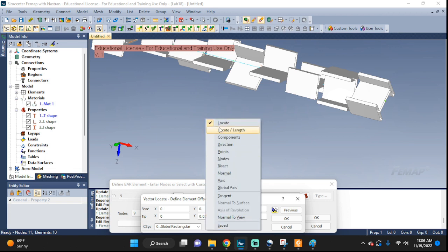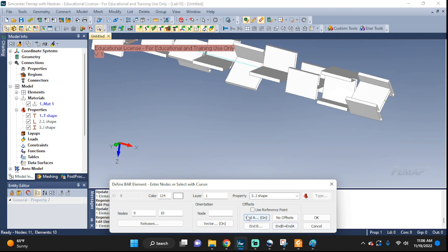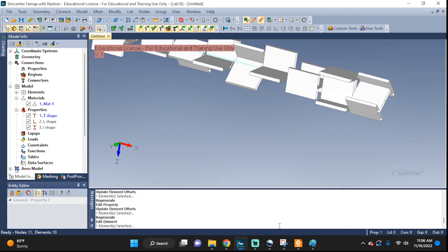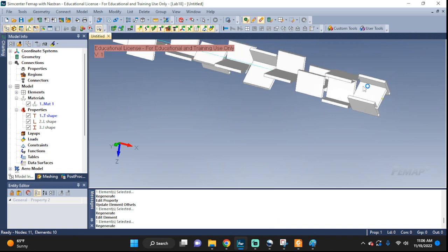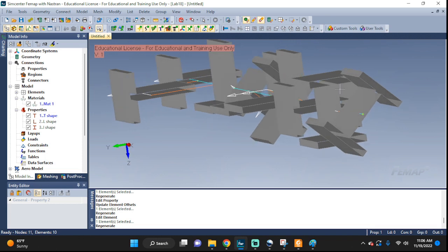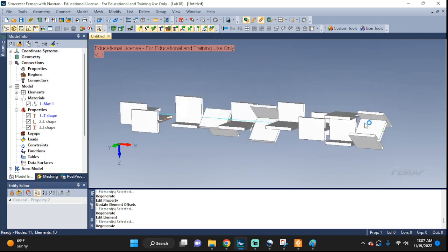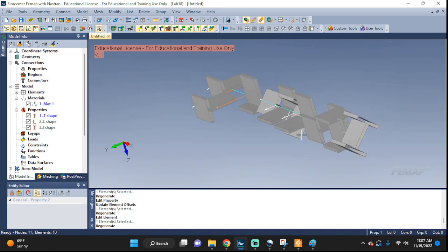Here I'm in the locate, and okay, and make A equal to B. There you go. If not, you'll just lift up one end and leave the other one where it is. Click OK, and it offset it. Control G to get rid of the old view. And there you have it. A bunch of offsets to practice how to move beams around and different types.